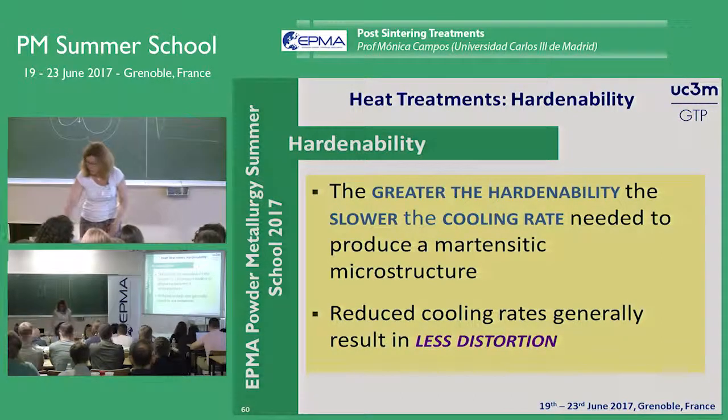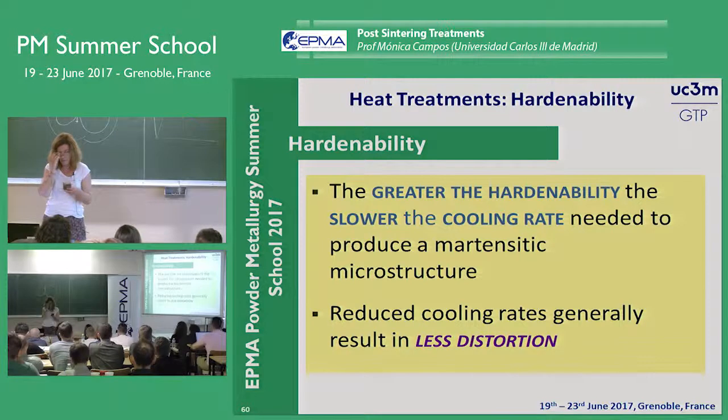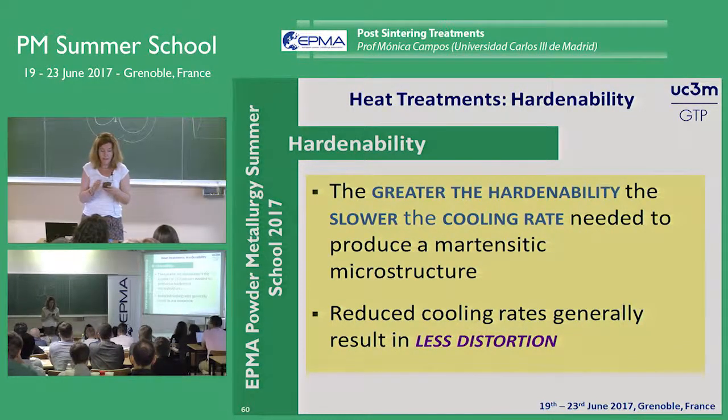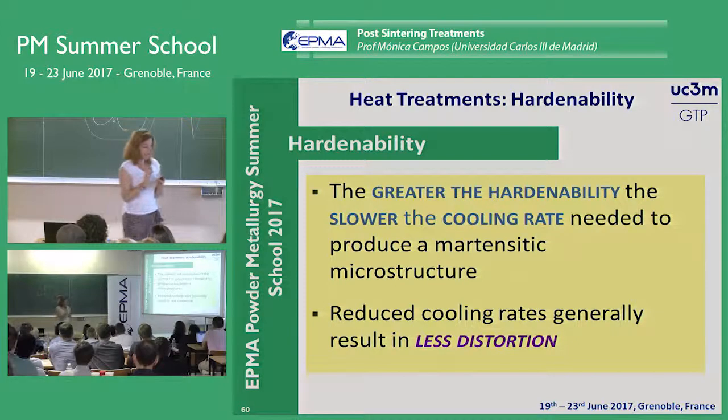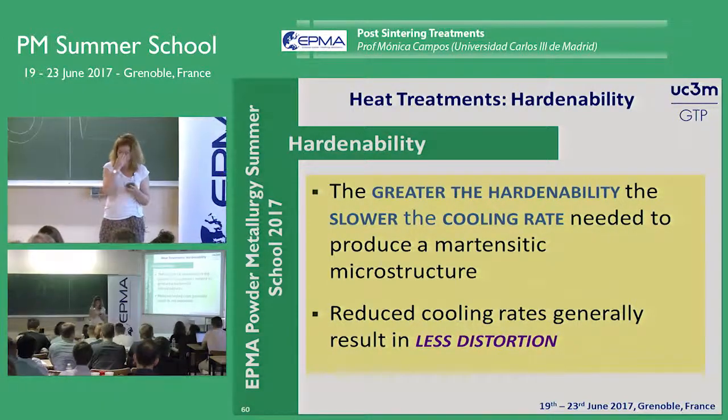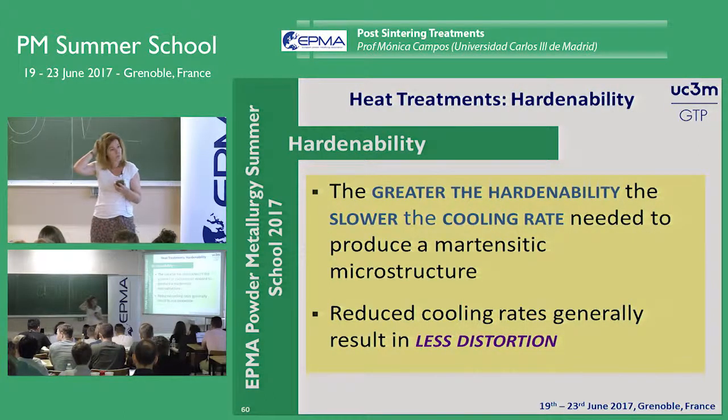I tried to put a video in my presentation, but I always fail. Then I invite you to type in Google "water quenching distortion." And in video, it's going to appear how, when a bar is cooled down in water, we are going to lose totally the geometry of the bar.